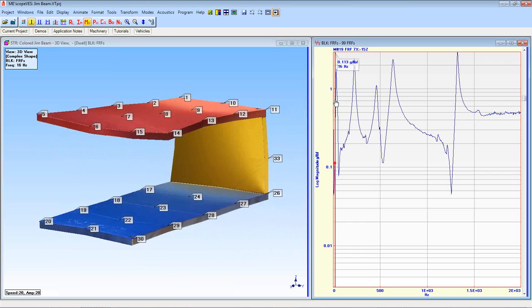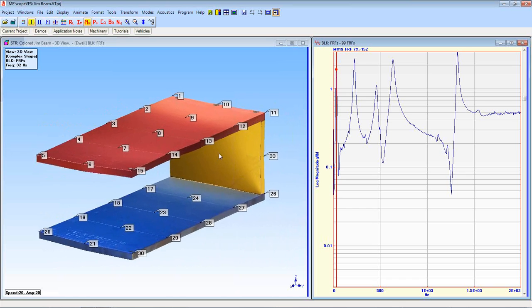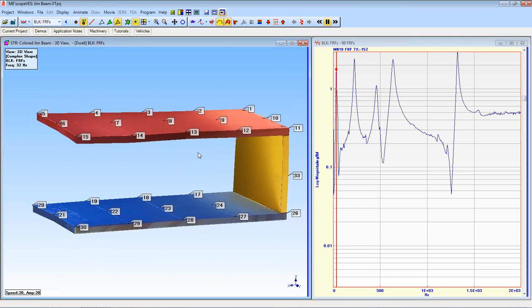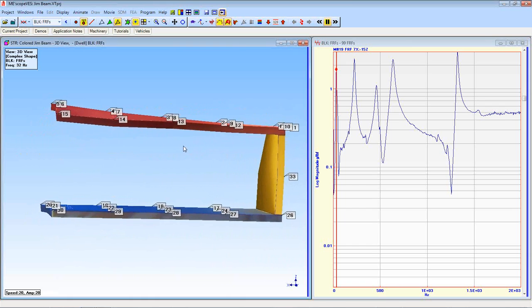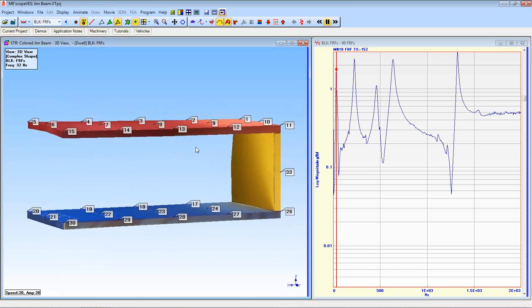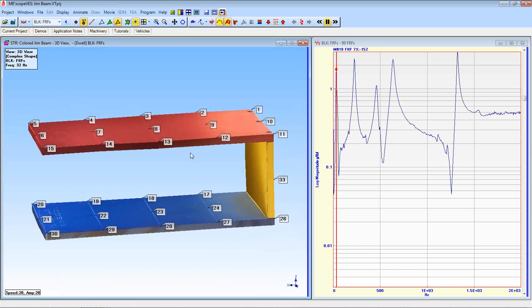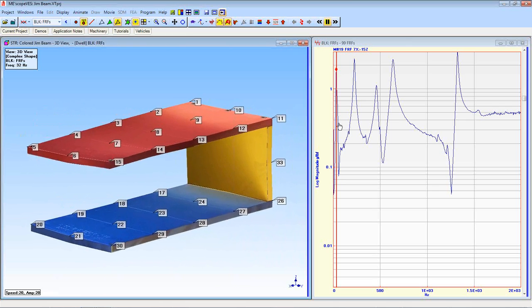If I move it up just a little bit, though, now I see what looks pretty good as what I would call rigid body motion. There's a little bit of flex in the back plate there, and maybe a little bit of strange behavior in one corner. But that plate is just essentially rigid body motion.